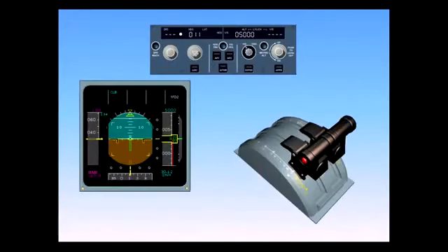When the aircraft is on the ground, the autothrottle system is necessarily disconnected. This is confirmed by the absence of any autothrottle indications on the FMA and by the extinguished autothrottle push button on the flight control unit. Thrust is manually adjusted by the crew as required to taxi the aircraft.